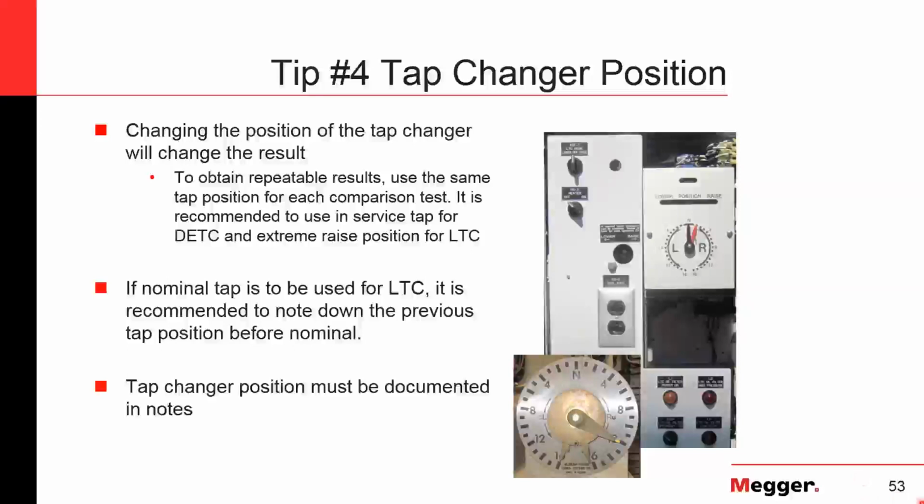If we go a little bit into the fundamentals of short circuit impedance testing, when you look at the nameplate of your transformer and it says, for example, short circuit impedance equals 10%, the meaning of that 10% is that under short circuit conditions on your secondary winding, with 10% of the nominal voltage on the primary, you will create 100% circulation of current on your secondary winding. So the idea normally is to apply very low voltage or very low current from the primary side to make sure that you don't create high current on the secondary.